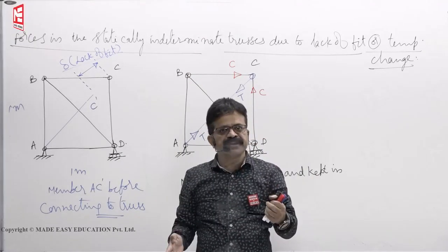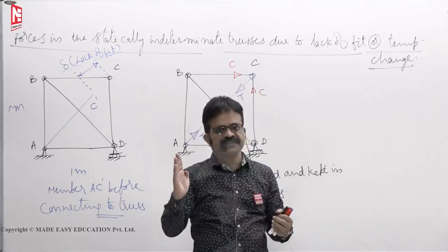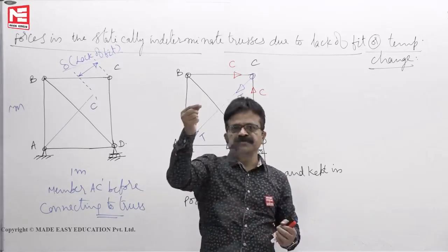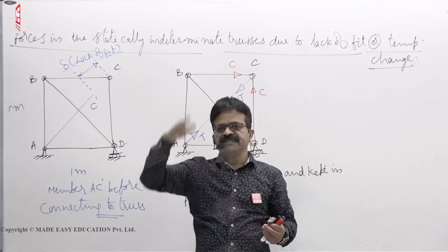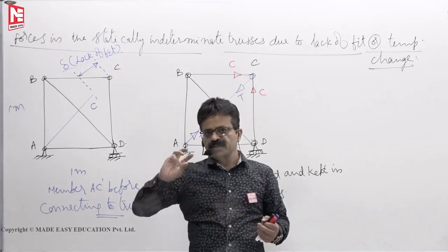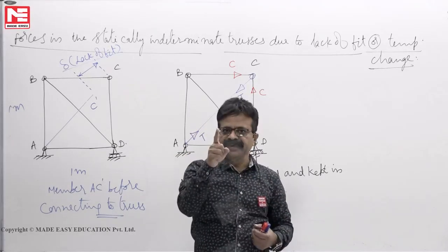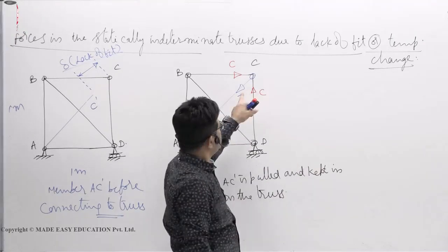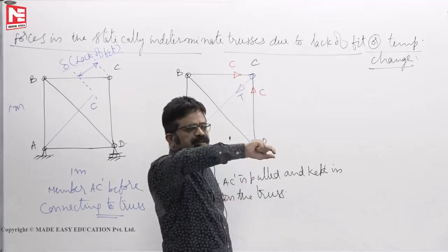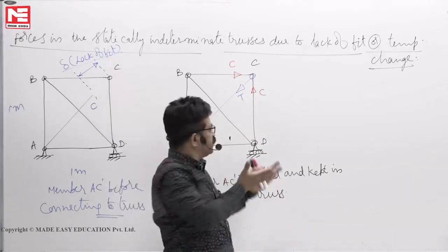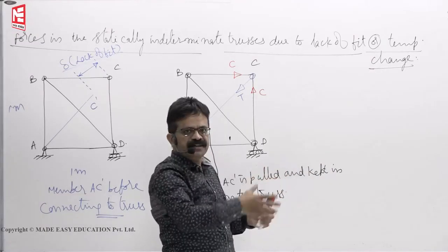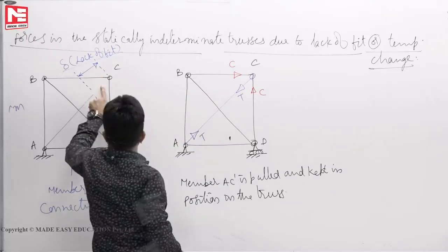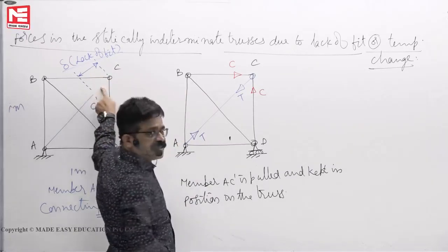If you take the free body diagram of the joint at one end, the washer end, then the tensile force and compressive force must balance. Otherwise, the washer will not be in equilibrium. So for it to be in equilibrium, the tube will be under compression and the rod under tension. Similarly here, when you pull the member with a tensile force, bolt it and remove your fingers, these are not moving anywhere else. That means it is still in equilibrium. Maybe after deformation, instead of this position, they will compromise and settle down somewhere here in between.